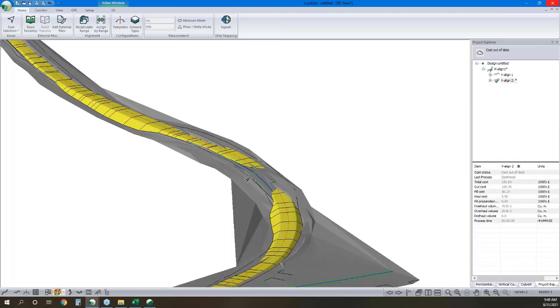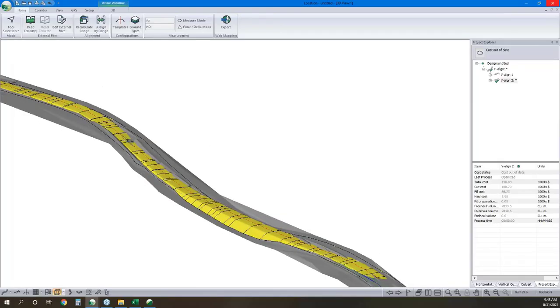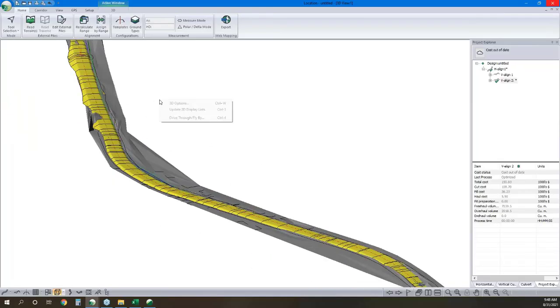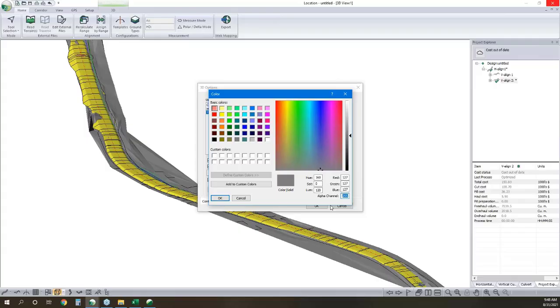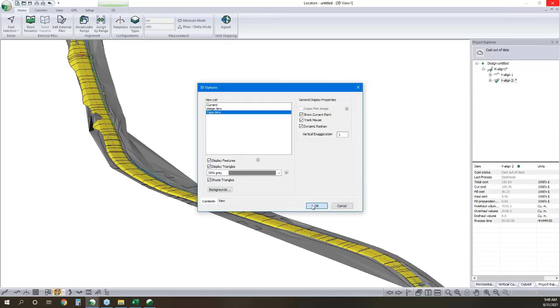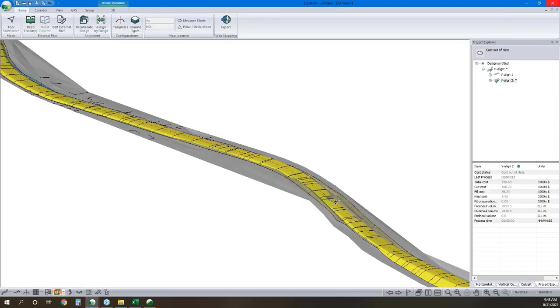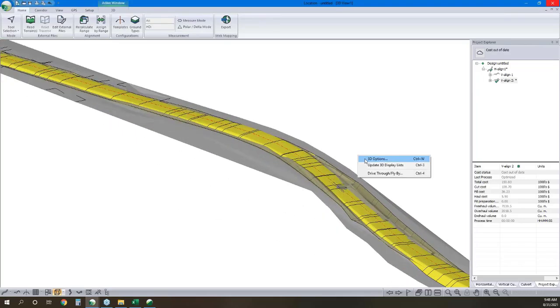So if I want to see what's happening in my ditch line or anywhere where I am in cut, I'm going to control the surface so I can see through it. So 255 is fully opaque, 0 is fully transparent. To get a good rendering, usually want somewhere around halfway between those numbers. Yeah, and if we go closer to 255, it'll be darker. So there we can see now inside our cuts and fills.